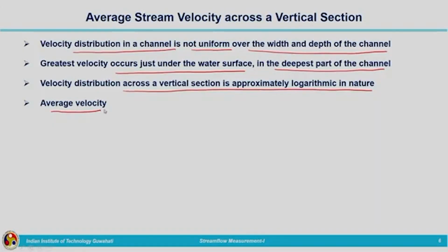I am not going deep into those details, how the velocity distribution will be in an open channel, that you might have covered already in open channel hydraulics. So, here what we want is the average velocity. For that, we will be measuring the velocity at different depths, and based on the velocity measurement, we will be calculating the average velocity.